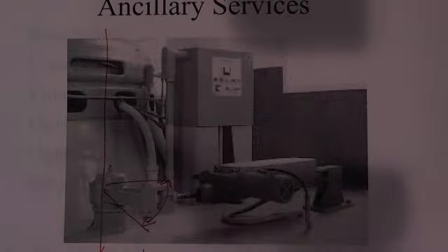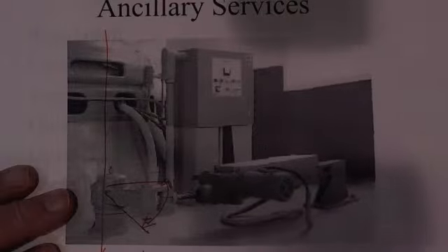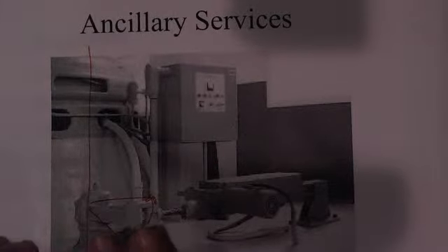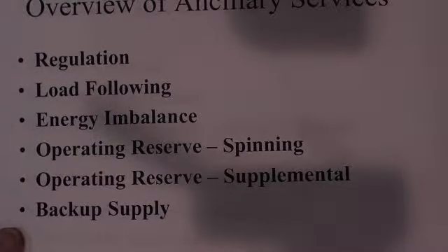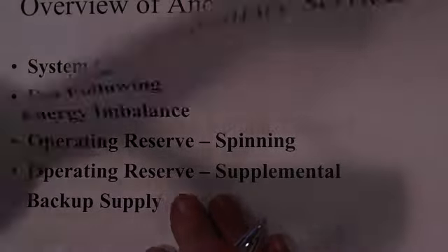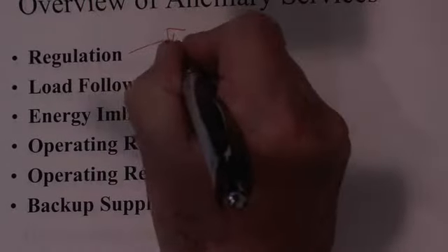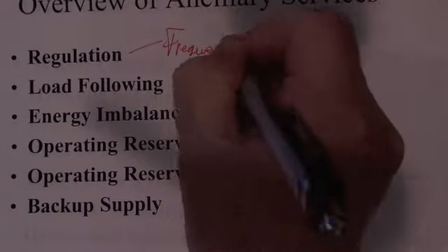necessary for frequency control. Remember, if you have an increase in load and this generator is participating in frequency, then this has to open the valve a little more, whichever way open is. I don't know on this figure. So there's an actual physical picture of something that's helping to supply an ancillary service. Here's a list of ancillary services, and I think it goes on for about 2 pages here. Now, regulation, of course, is frequency control.